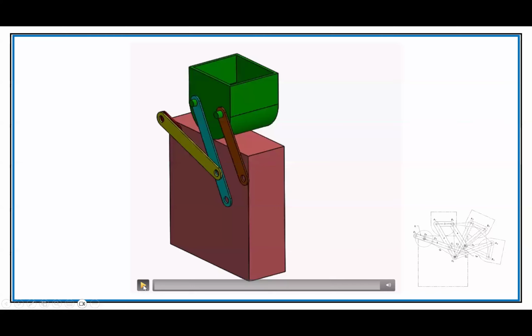As a real thing, it's nice to stay in one plane. It has all kinds of complications to be in two planes or in three dimensions, right? For this one, if we wanted to actually build it, there would be a lot of cantilever onto the ends of this link to try to keep it down there. And there's sort of a desire to make it symmetric so we can hold it, so we don't have to cantilever it. But quite often, a lot of times we'll have a problem of twisting and racking. So there's some concern, in reality, in that respect.